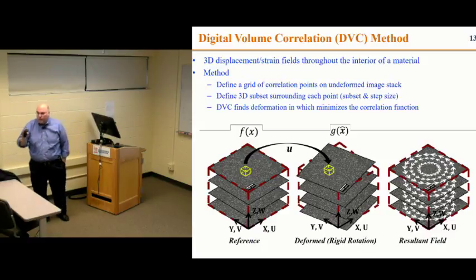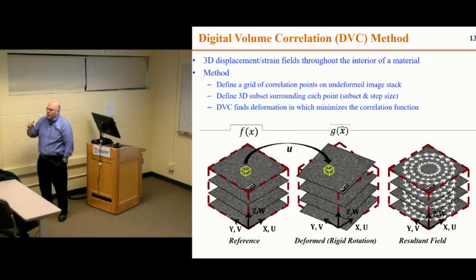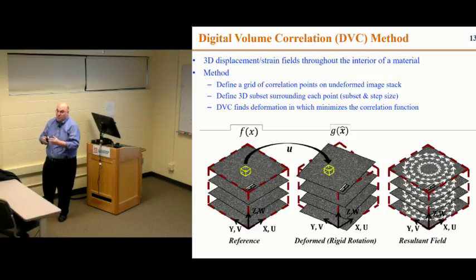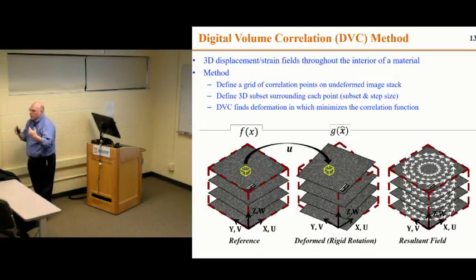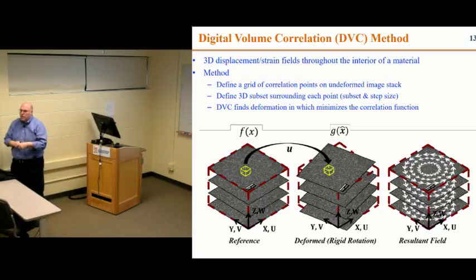Performing the scanning and getting a good image is one of the most difficult parts of this. Probably the most difficult part. If you have particles and components that have very high, essentially what you're measuring here is density, right? If they have very, very high density differences, then it's a problem, right? So what you're talking about is what is called shadowing, right? If you have, for example, a metal in there, and you try to scan that metal particle, there will be a very large shadow, in quotation marks, that is cast behind it. So it's a shadow in the X-ray range, right? And that would be a problem because you would basically have hidden areas of the sample and you wouldn't get a very good reconstruction. So yes, having shadow artifacts, ring artifacts as they call them and so on, are all significant problems that you have to deal with, right?